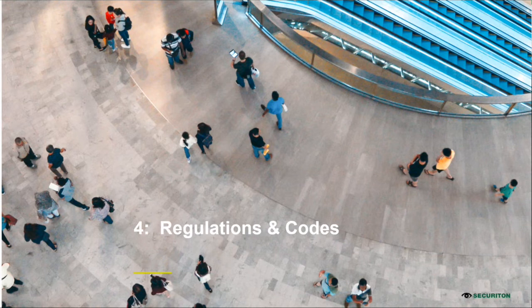I've got a few questions, Rohit, and the first question is, why is the ASD the recommended detection technology? Okay, so ASD is the recommended technology because it detects smoke at a very incipient stage of fire.